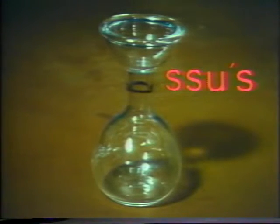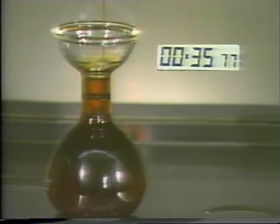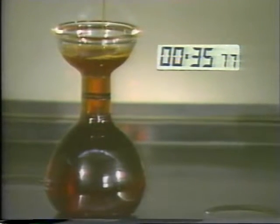The number of seconds it takes for the fluid to fill the flask to the mark on the neck is the viscosity of the fluid, measured in Saybolt Seconds Universal, or SSUs for short. As you can see, the viscosity of this lubricant is 35.77 SSUs.